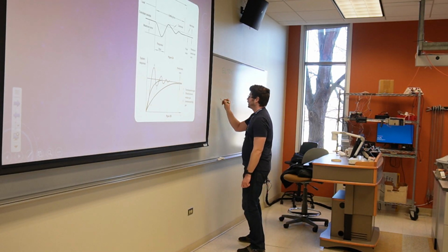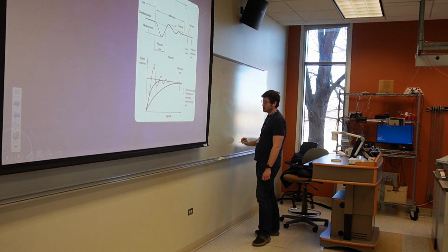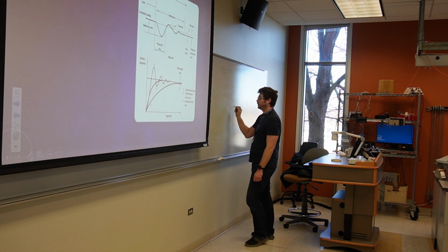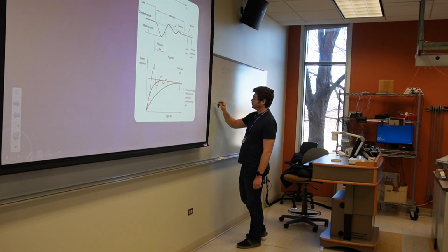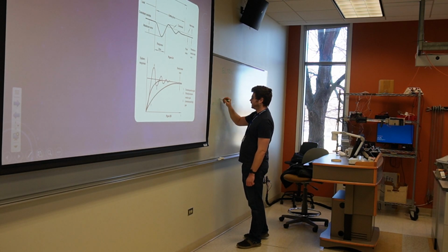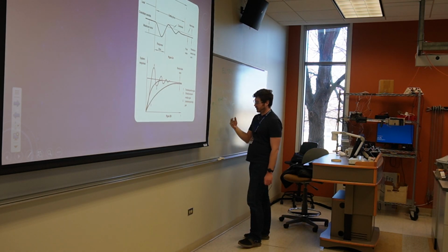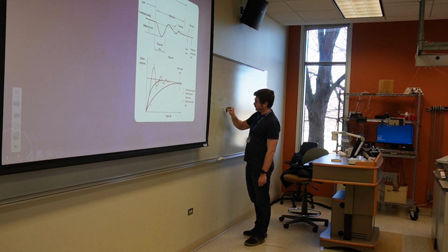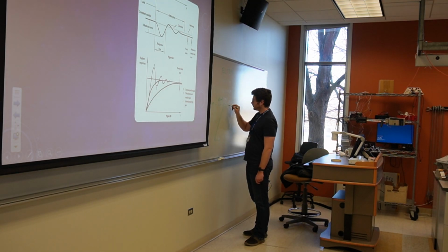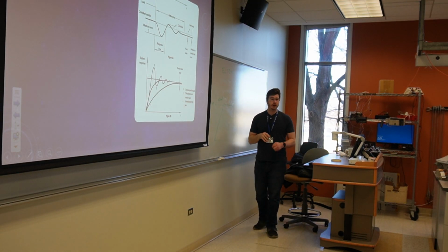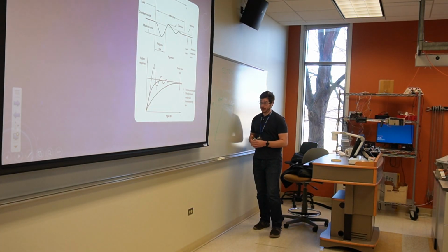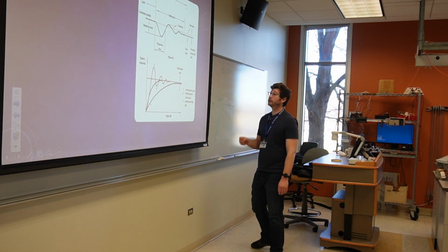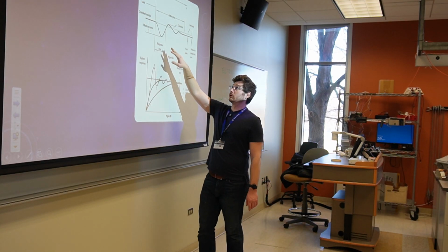For our speed controller, for example, if this is our set point, and this is 50 miles an hour, and we're starting at a dead stop, even as humans we will have some kind of control system in our heads that wants to get up to this line as fast as possible, overshoot as little as possible, and be as close to that set point over time as possible. All those as-possibles that I just said have vocabulary to them to track how well we are eliminating error over time.